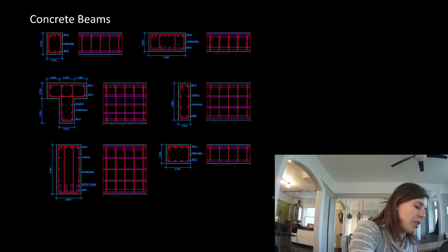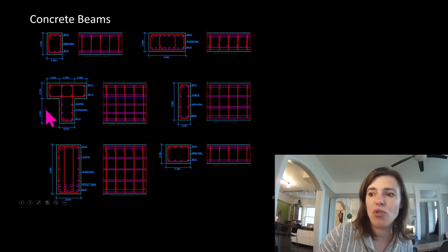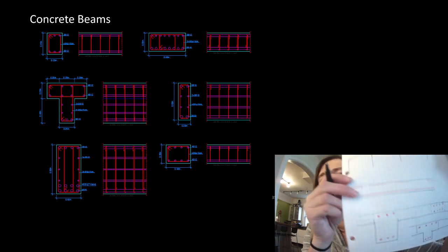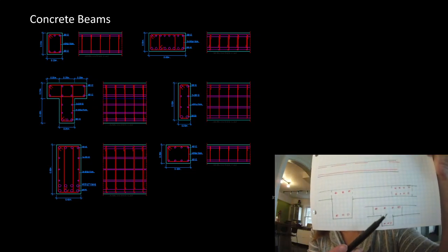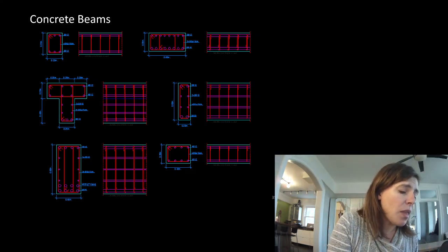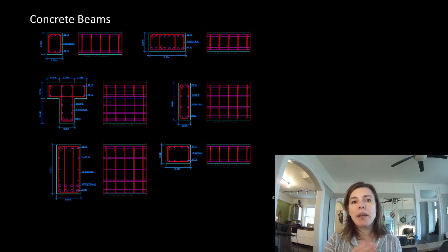We can actually also, and that is this drawing right here, make use of the fact that we're tied into our slab there by actually making some of the slab even more part of our beam, or a T-beam like that. So you can really work with concrete to take advantage of whatever you need depending on where you put your steel. But you need reinforcing steel where you have tension, you need concrete where you have compression, and you need steel and concrete where you have shear.